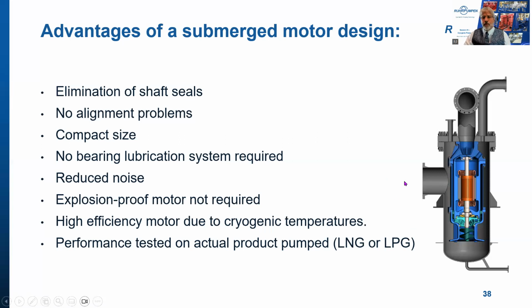Let me just show you the flow path through the pump. It comes in through the suction nozzle here, down outside through the barrel, turns around and comes in through an inducer here, and then a first stage impeller. There might be several stages of impellers. Discharges out here through a diffuser and up alongside the motor housing and out of the discharge nozzle.